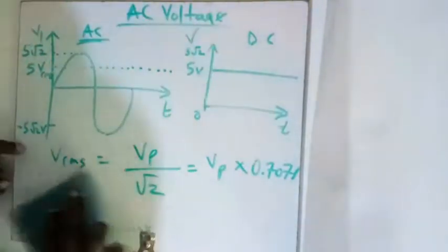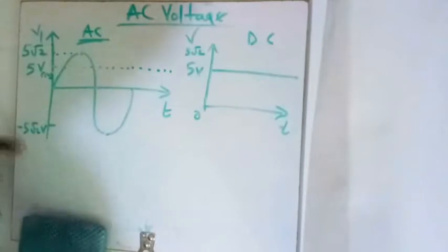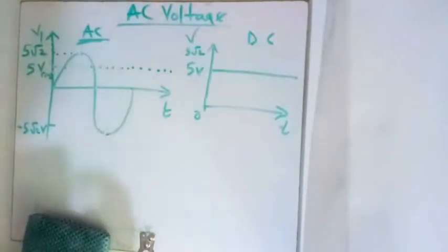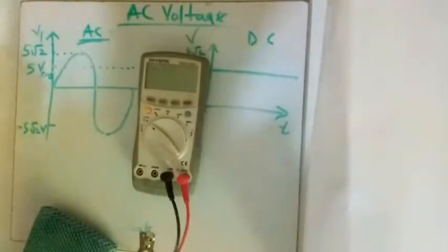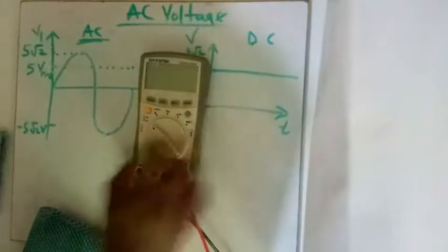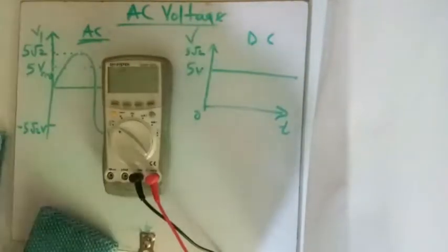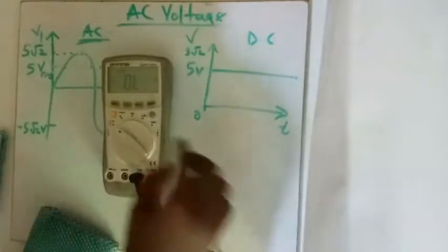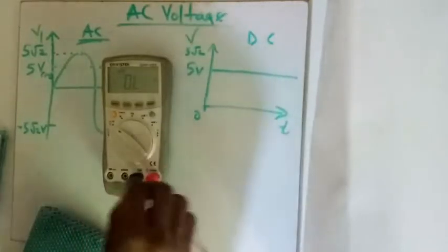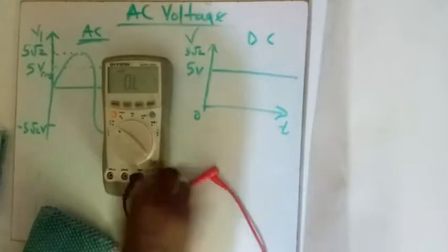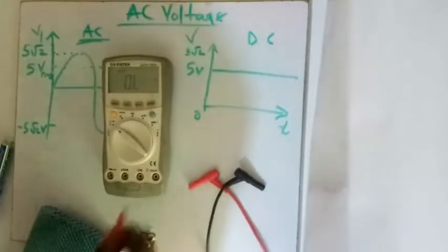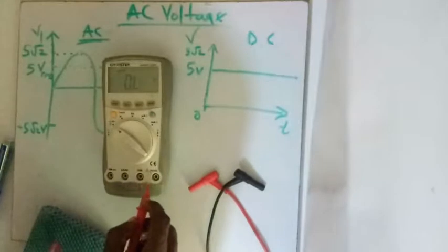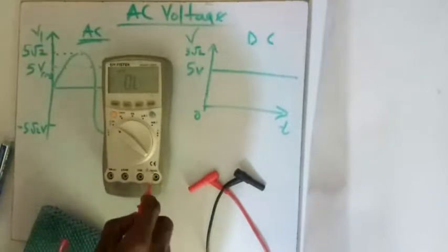So with that, last semester we went through how to use the multimeter to measure voltage, and of course we know that you turn on your multimeter first. You have different voltage ranges. Let's take out the terminals. Here, if you look at these symbols, you have Hz for frequency, V for voltage, and then this ohm symbol for your resistance.